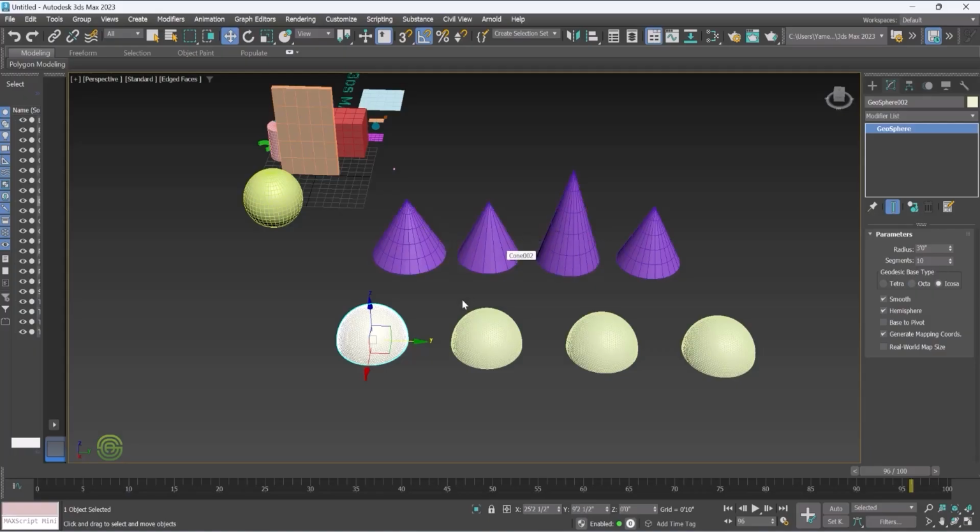But if you have designed a ceiling light, okay, if you have designed a ceiling lamp, and you want to copy it and place 10 lights in the other rooms as well, at that time you have to use instance. Because if you want to change the style of the lamp, you edit in one place.